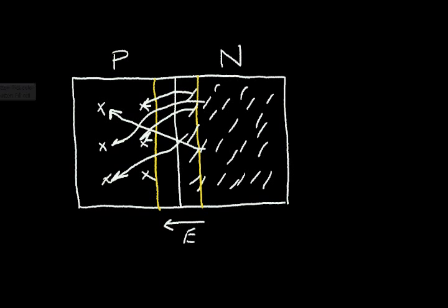So what happens is, because the P region is lightly doped, the depletion region extends further into the region that is lightly doped, where the concentration is smaller. And at the junction, the depletion region is smaller into the N region, where the concentration of carriers is higher. So let me erase this. Let's redraw this p-n junction region.